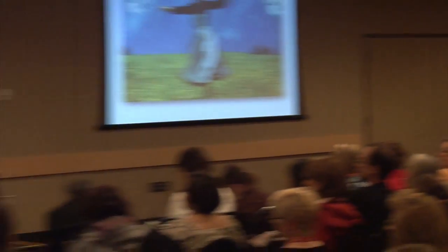Well, we obviously don't know that yet. We have no evidence at this time. The ozone levels after we're done can be measured fairly readily with handheld meters and very sophisticated instrumentation, and the amount of ozone is gone, it's zero. We bring it back down way below the EPA standard, which is 0.01 ppm over an 8-hour exposure.